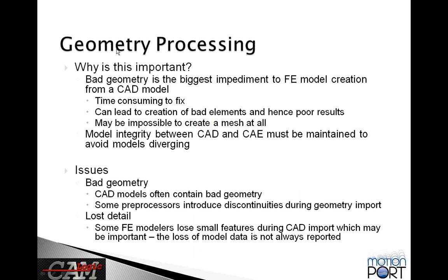Okay, Femap also supports geometry processing. Sometimes the geometry that comes from the CAD system has some problems with regards to meshing. It has to do with edges that may not connect up properly, and therefore the definition of surfaces and so forth isn't quite correct. So Femap can automatically take care of these issues, clean up the geometry, and prepare that geometry for meshing.